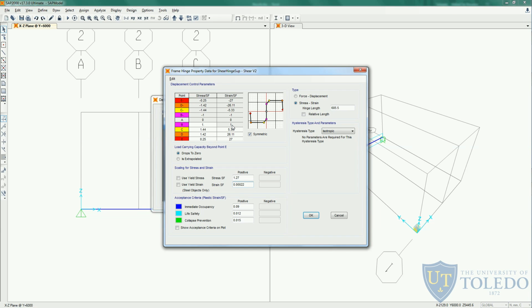However, it is stated in the SAP2000 manual that no matter what value you put here, SAP2000 will never consider it and it will always be 0. So you can leave it as 1 or leave it as 0, as it comes as default in SAP2000. It won't be considered by SAP2000. Also, we can see that our curve resembles the one we got from Response 2000.